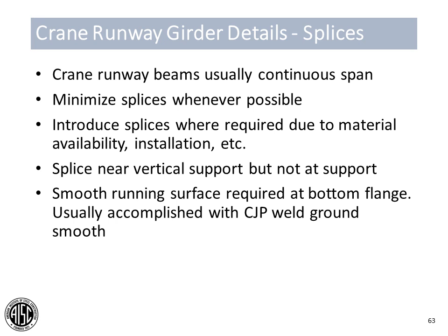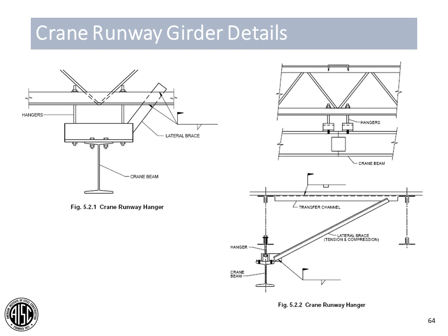And as I mentioned, you need to have a smooth running surface at the top of that bottom flange. So you typically will provide a complete joint penetration weld and grind that weld smooth. Just a couple more quick details.